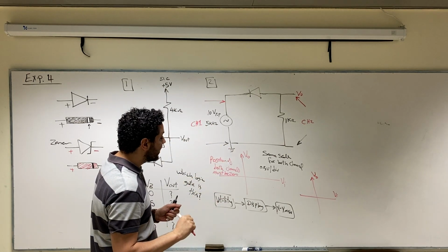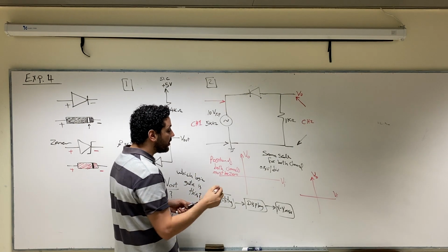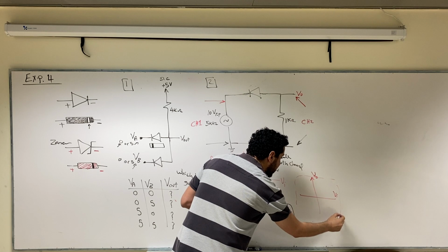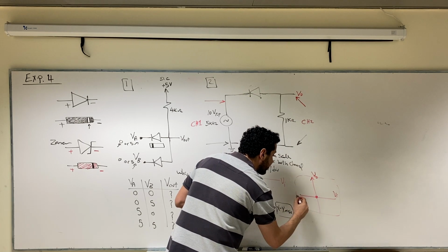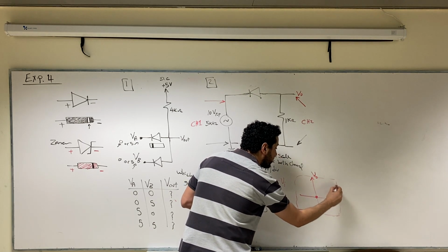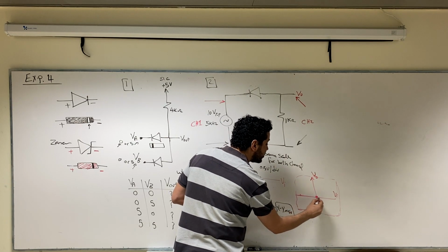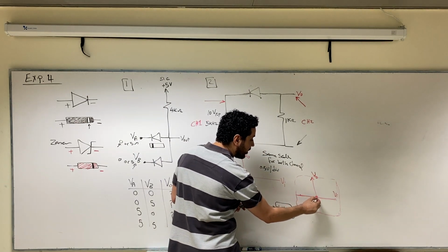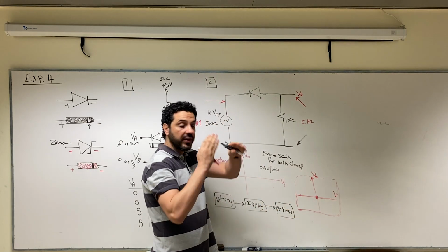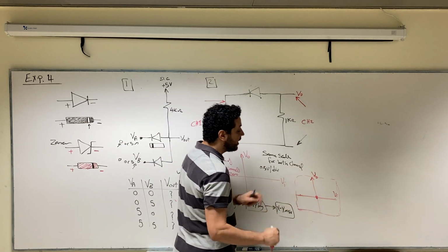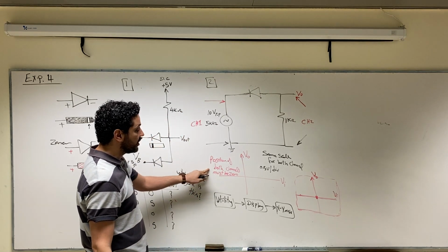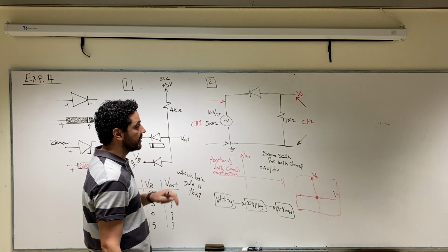Changing the position to 0 guarantees that the origin of your plot will be exactly in the middle of the screen. So this is the purpose of having the position at 0 for both channels.